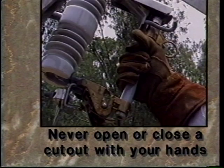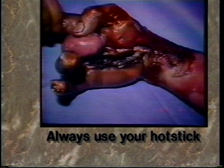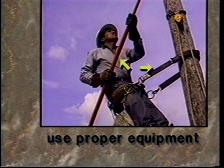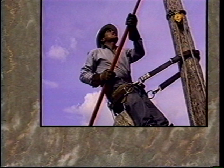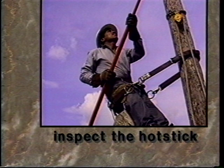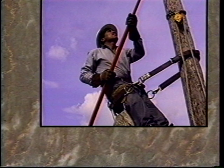Warning: never open or close a cutout with your hands, even if you believe the line is de-energized. The majority of electrocutions or electric burns happen on lines that are believed to be de-energized. Always use your hot stick. As in any portion of line work, a lineman must use the proper equipment, wear appropriate clothes, and utilize appropriate safety gear. Always inspect the hot stick to make sure it is in good condition. Always maintain a prudent distance from the cutout when opening or closing it.